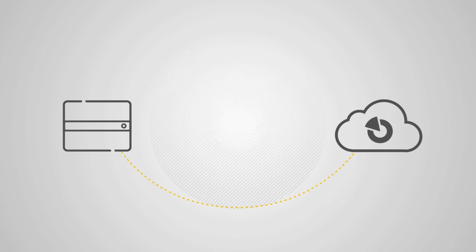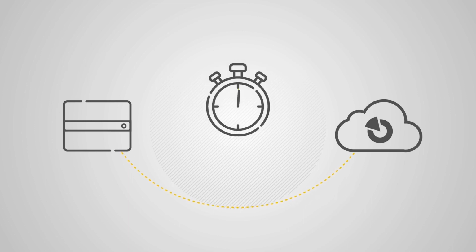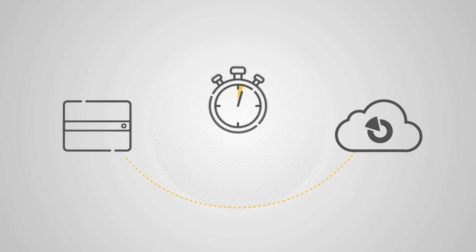Channel 2 acts as a controlling channel. It provides only data communication with no backup. It is used for controlling the system, and it sends the status of the system when changed: change of temperature, signal strength. Communication runs on Jablotron proprietary protocol and is secured by a persistent connection with only a 15-second heartbeat without confirmation. Delivery of the information is not confirmed.